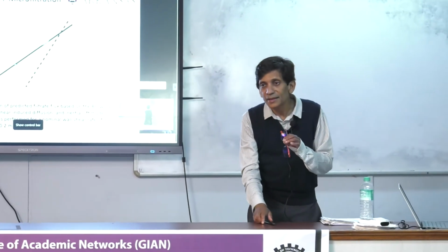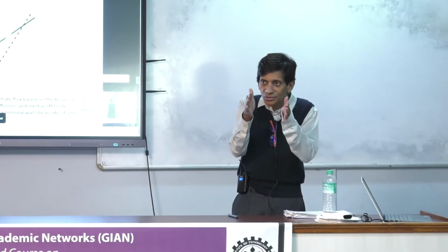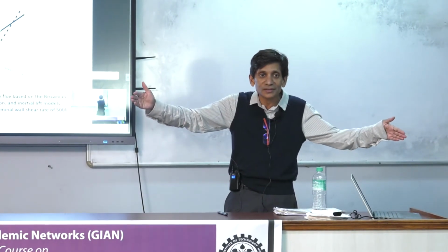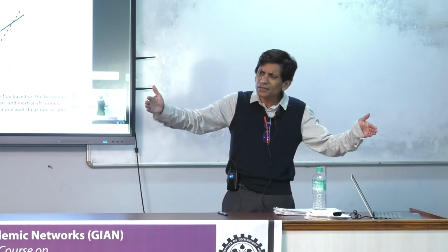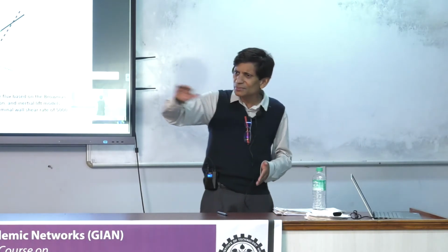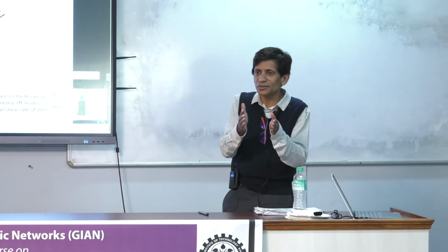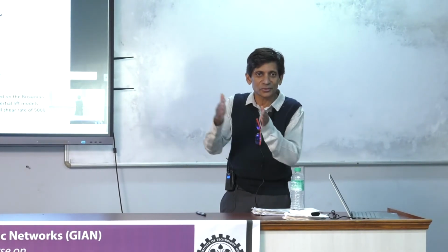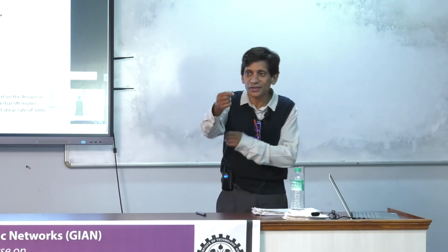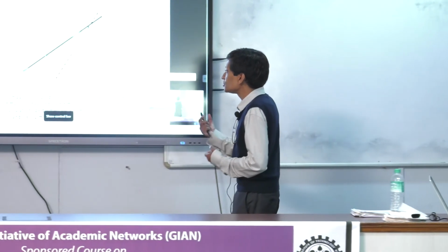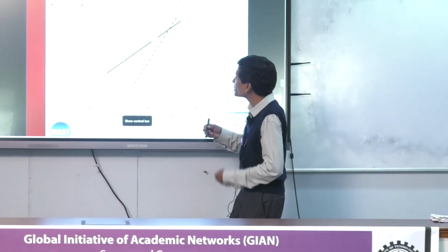It means that if you want to maximize your flux, you want short fibers or short membrane paths, not very long ones, right? Because the longer the path, the greater the concentration polarization boundary layer that forms. The other side of it is that if you have it too short, it's going to be a huge expense, because you've got modules in series, you've got to have connections, so there is a trade-off. But with long modules, you pay a price with lower average fluxes.